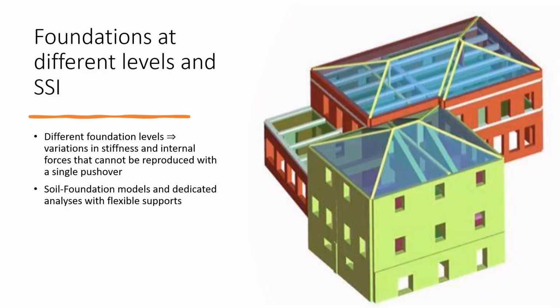And in the case where soil-structure interaction is relevant, we need to include soil foundation models in the model and perform dedicated analysis with flexible, deformable supports. This is something that we can do in a quasi-static fashion, but its actual representativeness would be in the time history, in the dynamic response.